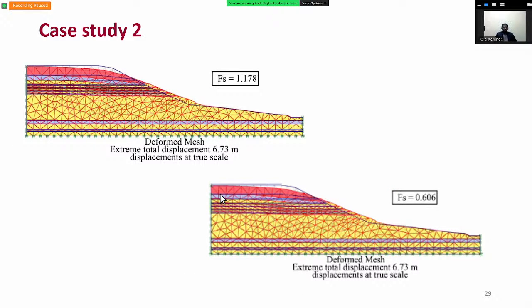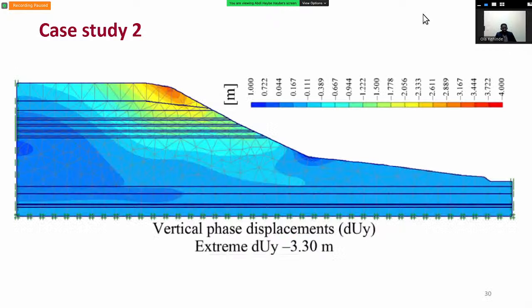Calculations are carried out under two conditions: dry state and saturated state. Initially, for this study, three software packages were used for computation and simulation: Plaxis, GeoSlope, and Terran. But for the sake of this study, I limited it to Plaxis. Next slide, please. Then for the dry state condition, the shear strength reduction method according to the Mohr-Coulomb criterion underestimates the factor of safety by 2%.